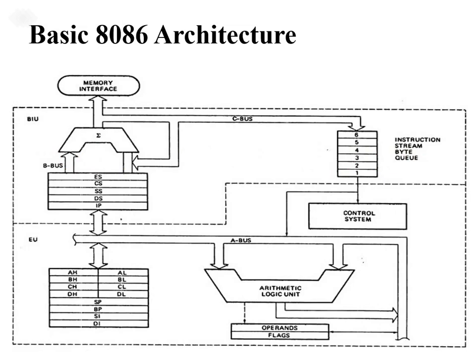This is the block diagram of the 8086. It is divided into two functional parts. The upper part is known as the bus interface unit and the lower part is known as the execution unit. If you observe it properly, this whole architecture is connected to your memory, right?